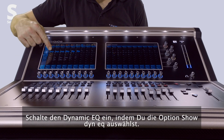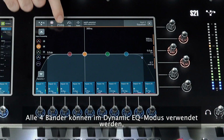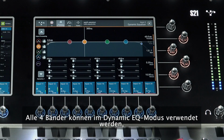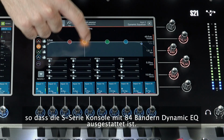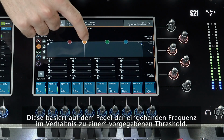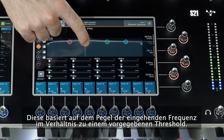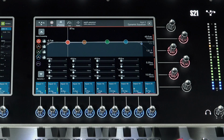Turn on dynamic EQ by selecting Show DIN EQ. All 4 bands can be utilised in dynamic EQ mode, providing a massive 84 bands of dynamic EQ in your S-Series console. In this mode, EQ adjustment can now be applied dynamically. This is based on the level of the incoming frequency relative to a predetermined threshold.